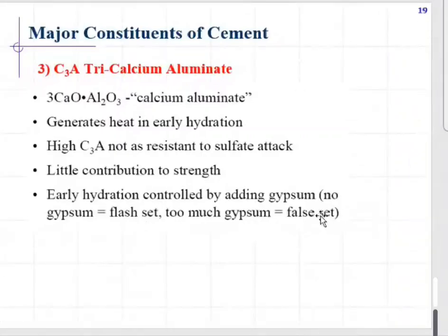One is flash set, another one is false set. Flash set means no gypsum. Flash set means, gentlemen, you put the water into the cement. What happens? Cement, within no time, makes itself stiff. And if you try to remix it, it will change its characteristics. So this flash set is never desirable.